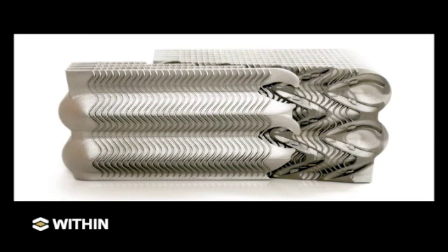Now, we also have the air running vertically here, and you'll note by the angles here that the air has to be forced through. It's not easy, and this is actually a conceptual heat exchanger for a Formula One car, and there you actually want to force the air through the component. Now, with this part, this was essentially, again, 95 to almost 100% material usage. So no manual work, no manual labor. You just slice it off, and the part's done.